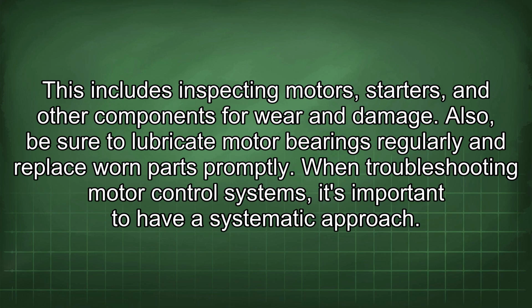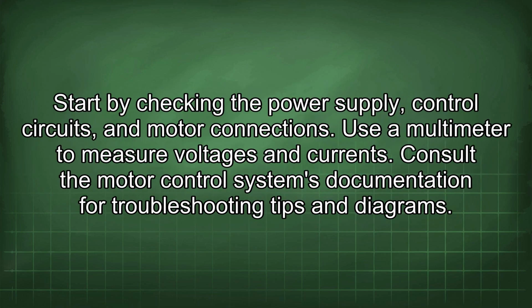When troubleshooting motor control systems, it's important to have a systematic approach. Start by checking the power supply, control circuits, and motor connections. Use a multimeter to measure voltages and currents. Consult the motor control system's documentation for troubleshooting tips and diagrams.